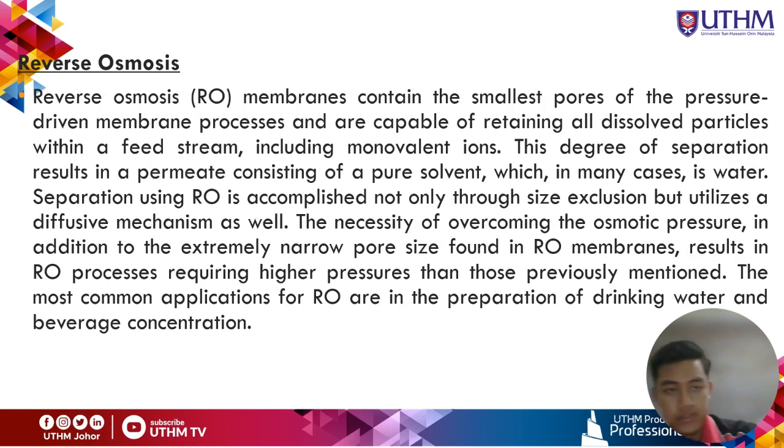For reverse osmosis, the membranes contain the smallest pores of the pressure-driven membrane processes and are capable of retaining all dissolved particles within a feed stream, including monovalent ions. This degree of separation results in a permeate consisting of a pure solvent, which in many cases is water.